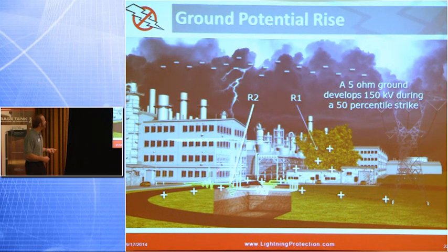Well, this ground here is still feeling the effect of that current. It's in the same vicinity of that current flow, but it's at a much higher resistance. So it's not tied to this ground. So maybe this ground over here is 300 kV because it's twice the resistance. Now all of a sudden, they want to equalize each other. So if I've got a resistance between this ground here, which is the earth, and that ground, and I have voltage potential difference, this is at 150 kV, and that's at 300 kV, I got a 150 kV difference of potential between those two grounds.